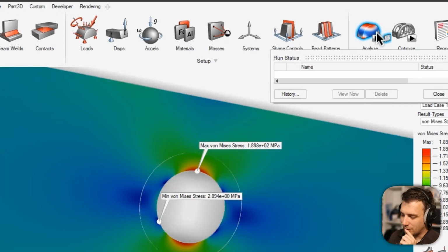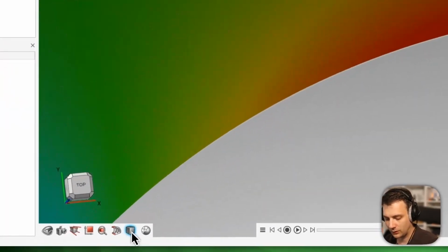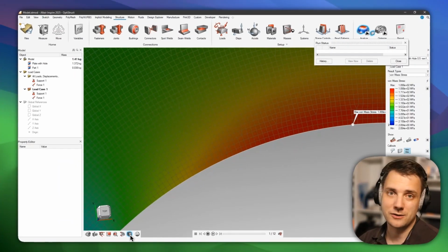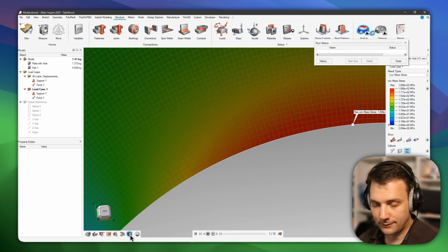Besides that, also from the Inspire perspective, if you want to see the mesh, you should just click here, right? You should know that with Inspire, you see the mesh only when you run it, because the meshing is done when the solver runs. Before that, you cannot see the mesh. That's a contrast to HyperMesh, because in HyperMesh, you can see the mesh before you click the run button. But here you have to just click run and then go into the input folders to check the results.